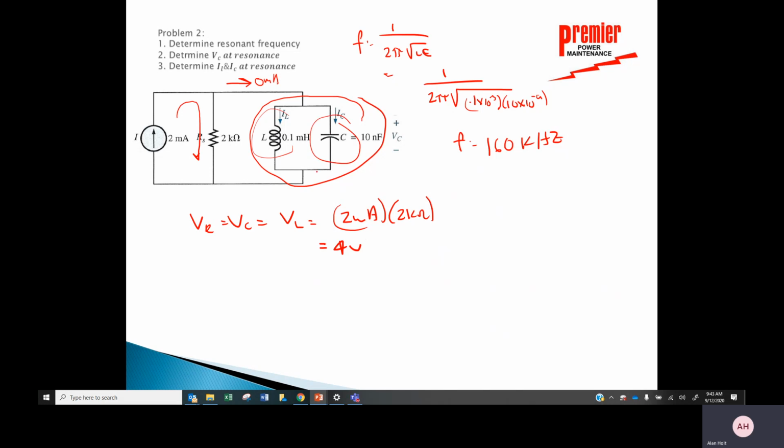And I do. So even though I've got 0 current flowing through here, I've got some current flowing in this inductor and this capacitor. When I do the math, I find out that for these components, X sub L equals X sub C, about 100 ohms.